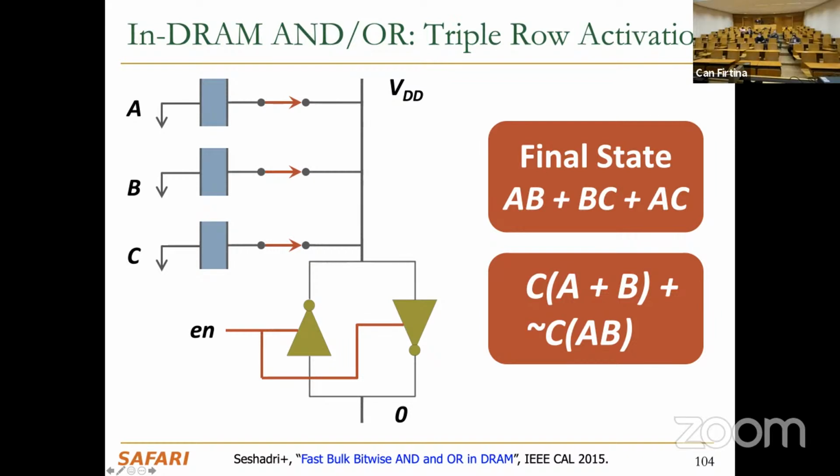And with NOT. Well, if your address is 10 bits, it's really a tree of AND gates. Okay, makes sense. And those AND gates need to be large, and they are implemented in the DRAM process, which is not friendly to logic. As a result, they occupy a lot of area in DRAM.